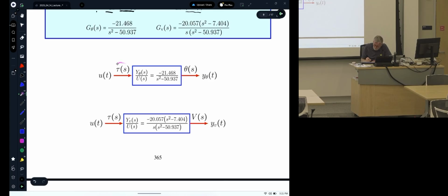We have one motor. Well, because we're doing a planar model, there's really one motor for each wheel, but we're going to have the motors moving in sync. So we're just moving in the plane. So we have one actuator, the torque on the motors, and yet we want to control two things: lean angle and speed. That's hard, okay? One actuator, two objectives.